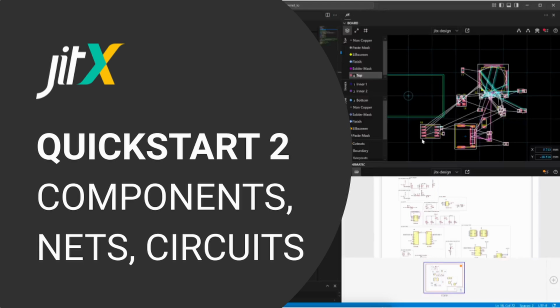How to find and use circuits from libraries, as well as learning how to model components from scratch using EEPROM as an example. We'll make a reusable circuit for that EEPROM using nets, ports, and bundles, and we'll also learn how to automate the supply chain with parametric parts like capacitors.